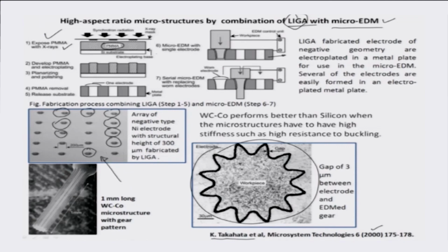In the first step, the mask is realized using laser patterning or some other method, with which a small gear-like structure can be made, typically as openings. So the mask has openings in the shape of micro internal gearings.